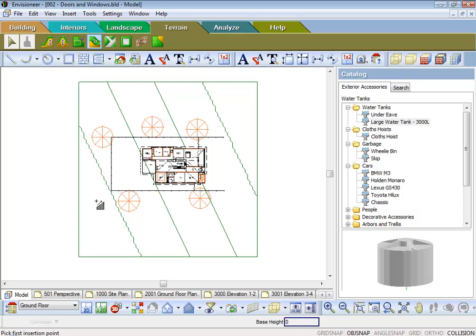So now I'm still in the command of the slope, and you'll notice the arrow pointing up on my mouse there is up. If I go from that point there, which is a metre, and come up here and pick another point, that's going to give me another 1500 rise from that point to the end of the arrow. So there's another 1500. So now I've got 0, 5, 10, 15, 20.